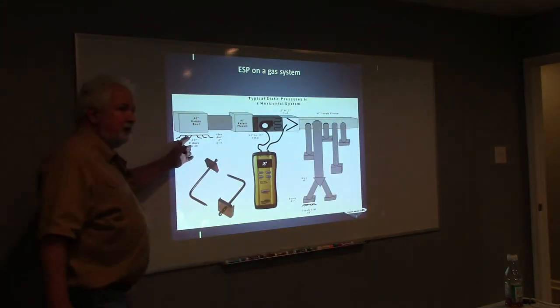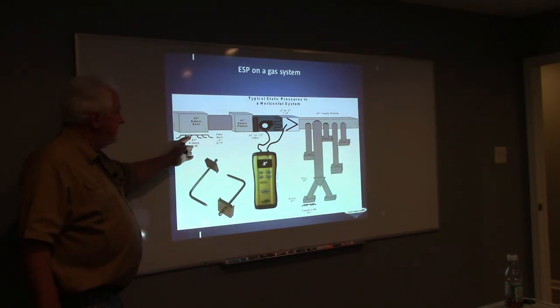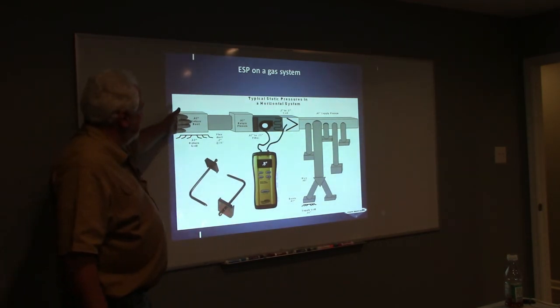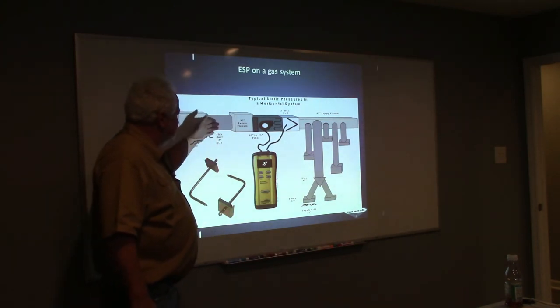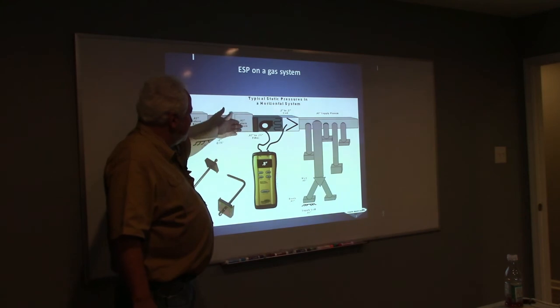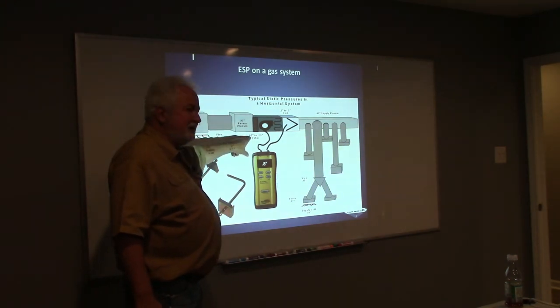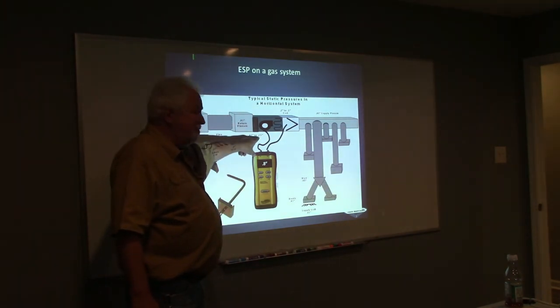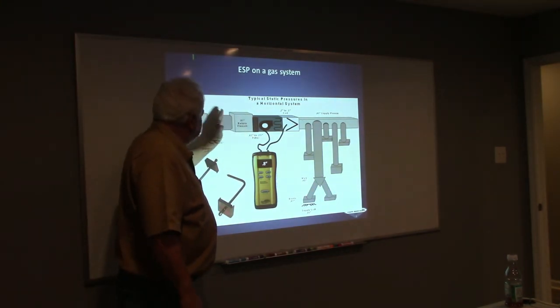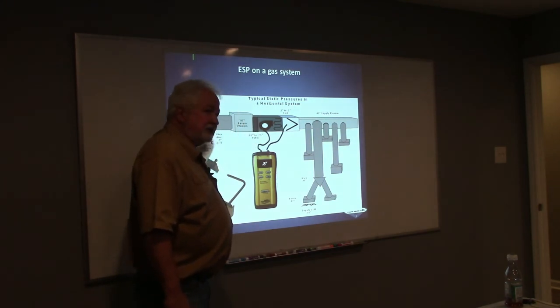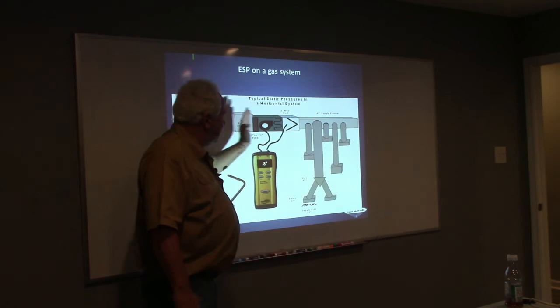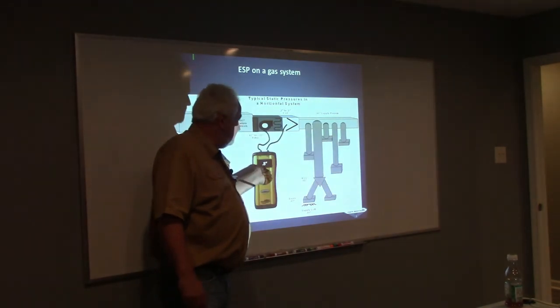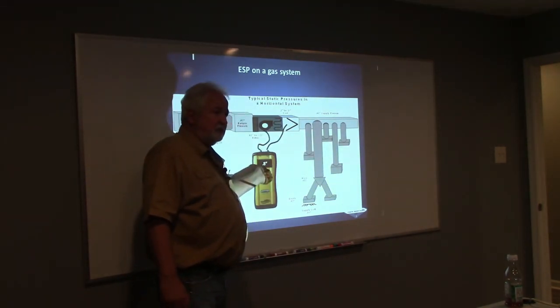Return air grill, look, again, 0.02. Nice. Good air through there. Return air boot, I've got some resistance there. The flex duct, look, there's a lot of resistance there. Return air plenum, just a little bit. The filter can be anywhere from 0.07 to 0.25. That's a lot right there. So all of these add up to the resistance on the return side. Resistance on the return side plus the resistance on the supply side give me total external static pressure.